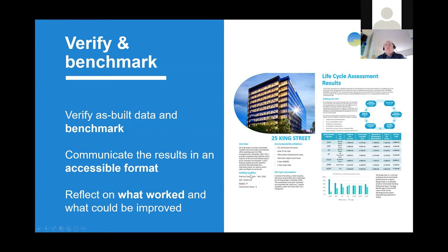They've done a life cycle assessment based on life cycle assessment methodology. You can see here the global warming potential of the whole building, cradle to site, using the materials, construction activities, operation and maintenance, and end of life. So you get a whole of 60-year total for the reference building and the building they actually built. And they've done some comparisons with their reference building here. I think they've done about 50 LCAs, mainly for the Green Star rating systems, but they do it themselves internally to improve, measure and benchmark what they've done and how they can improve.